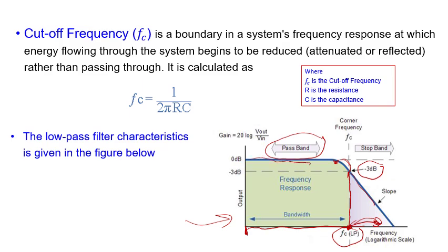If the voltage drops a little bit, it is no problem. That little bit is given here as minus 3 dB. Regardless of the detail of this dB, I just want you to know that we will allow the output magnitude to drop a certain amount, and then we will take the cutoff frequency at this point. We are not taking it at that point, no. We allow some drop. So that's the characteristic of the low pass filter.